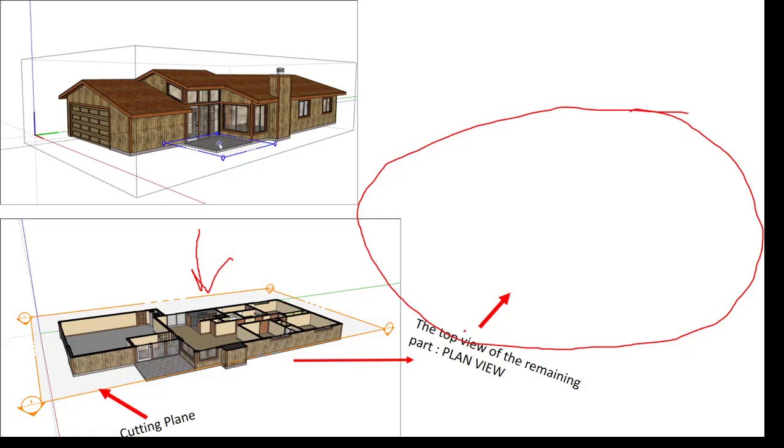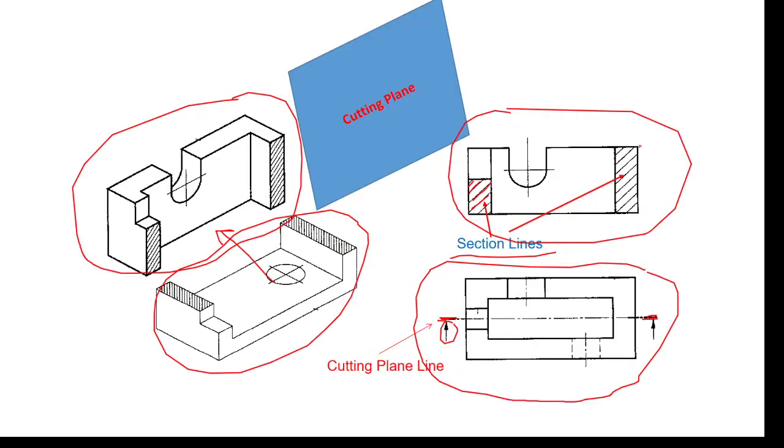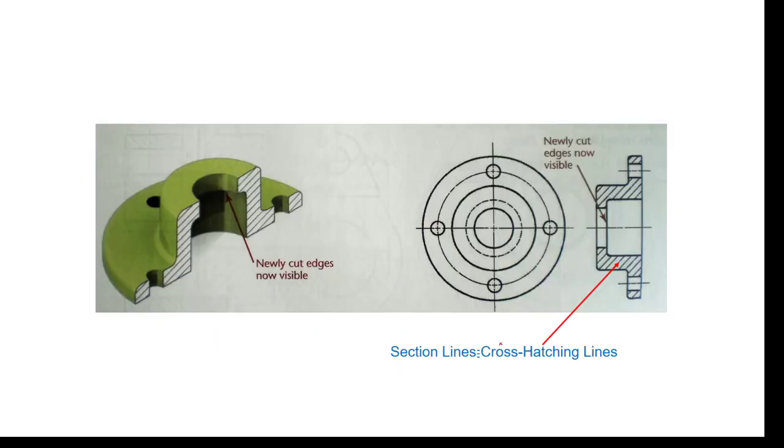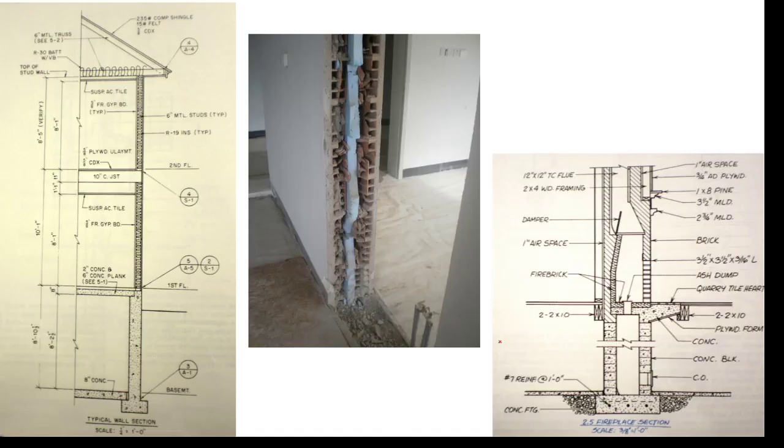In mechanical engineering drawing, the same style, equally spaced inclined lines, can be used for any kind of material. But in architectural and civil engineering drawing, to highlight that there are different layers on an assembly drawing, as a building is an assembly, architects and civil engineers use different hatching styles.